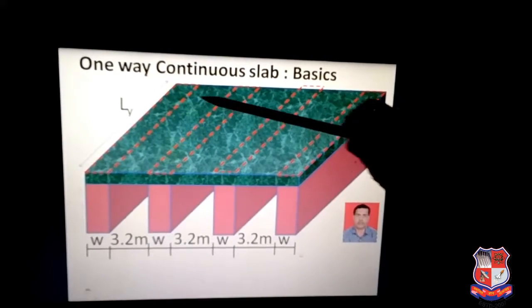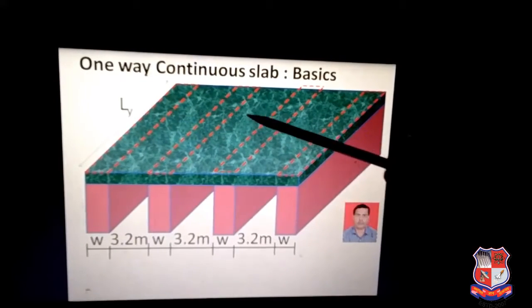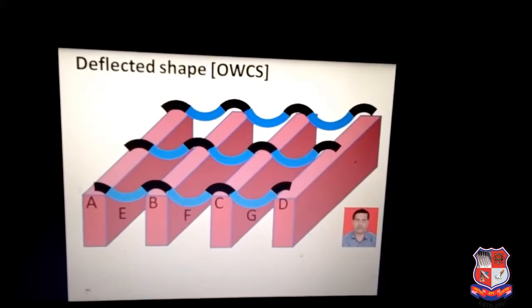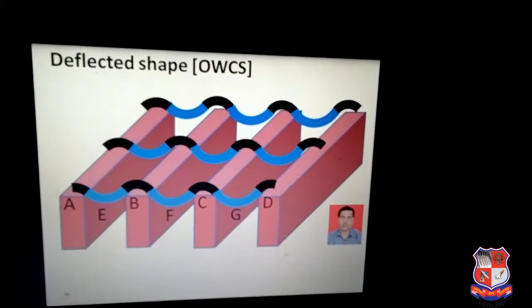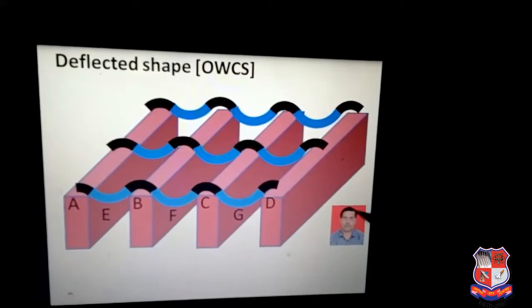Now between 2 supports we have the one-way slab portion, and this slab area, the second span area and third span slab area are each to be designed by a collaborative method as per guidelines of IS 456-2000. Now the most important aspect of a one-way continuous slab is its deflection pattern, that the one-way continuous slab is going to deflect once it is fully loaded from top.